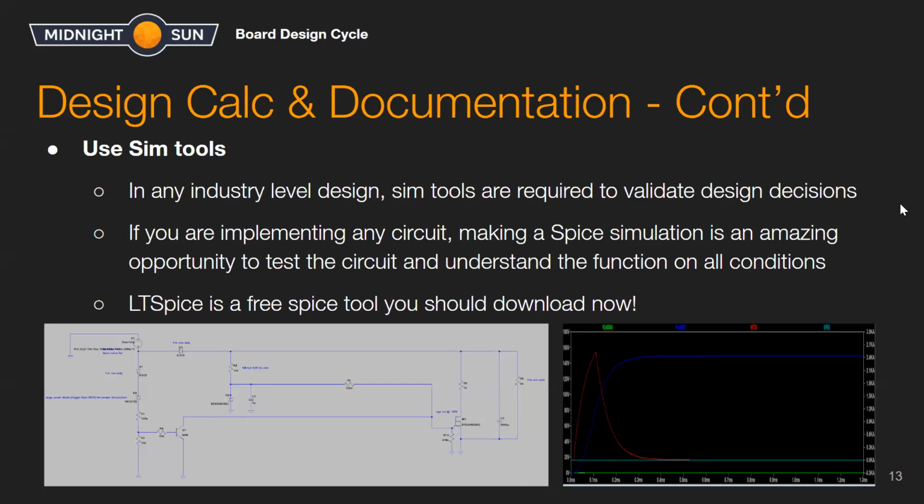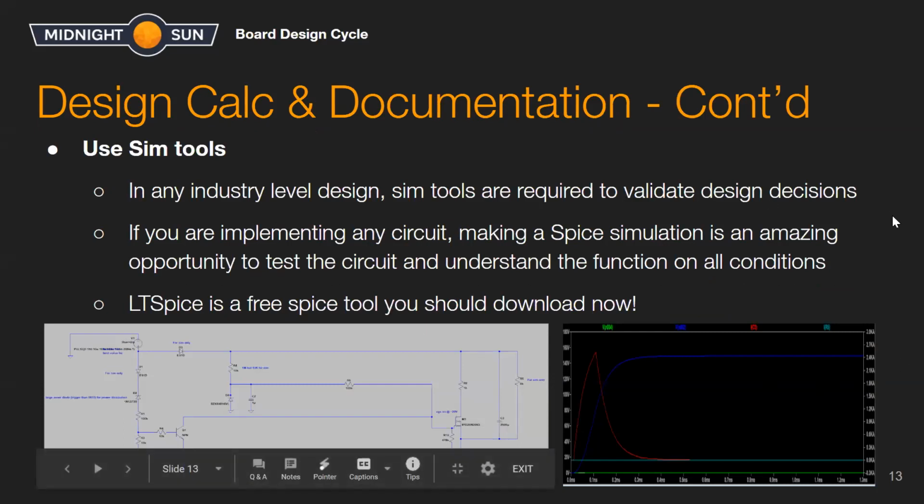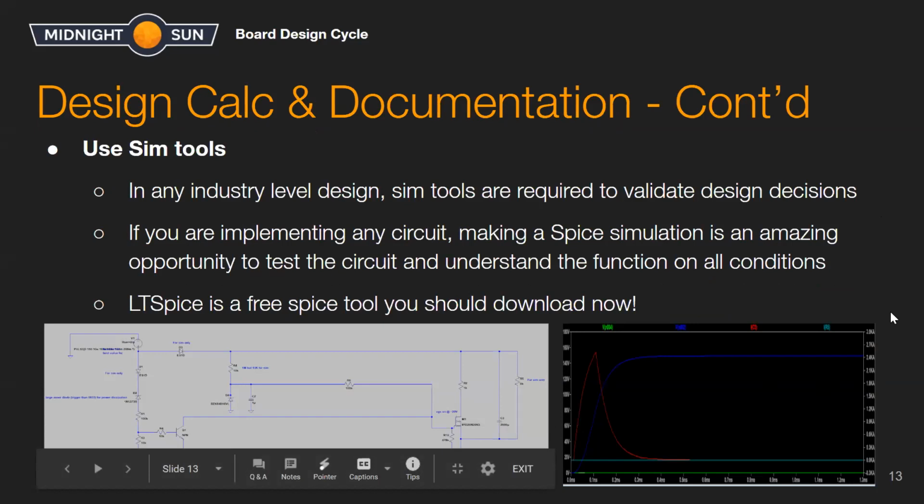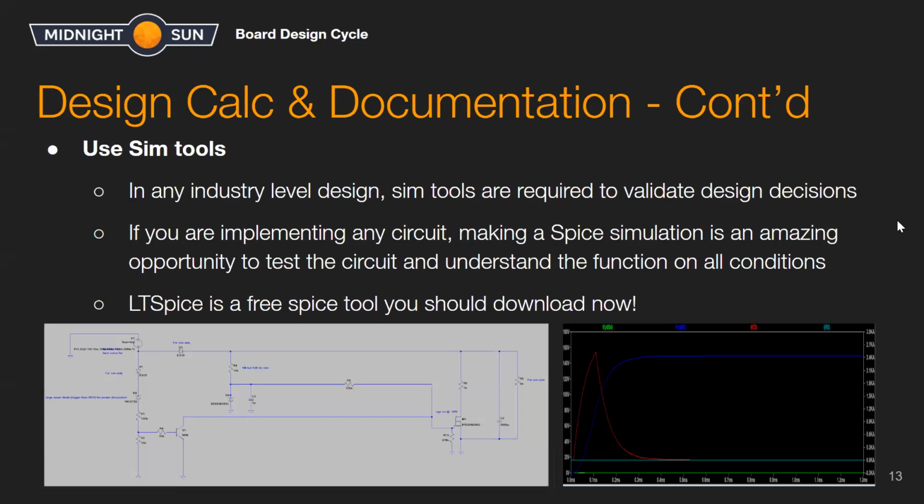Sim tools are an amazing way to know what measurements you're going to expect. So this is one of Ashmika's sims that she did. Ashmika, do you want to talk about this? Yeah, sure. So SPICE sims are especially useful for a variety of things. One thing is to measure the current and voltage expected at every node of your design, and therefore you can spec the components you need much easier.